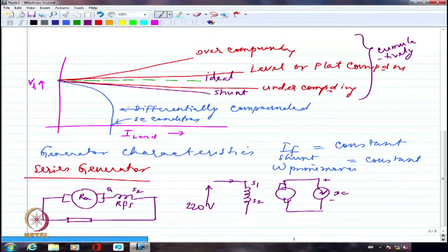And also please realize that this is going to have a back EMF in all probability, or generated EMF, even if I am looking at it as a motor. So if I look at the series field winding and the armature current, the armature resistance along with the load resistance are limiting the current, all of them put together. So EG divided by R series plus RA plus RL. All of them are coming in series. That is what is limiting the current. So if I just apply 220 volts to the series field winding, there is nothing to limit the current properly.